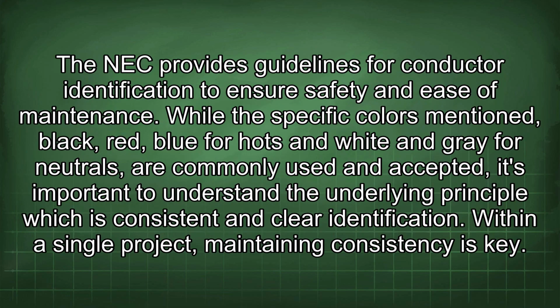The NEC provides guidelines for conductor identification to ensure safety and ease of maintenance. While the specific colors mentioned, black, red, blue for hots and white and grey for neutrals, are commonly used and accepted, it's important to understand the underlying principle, which is consistent and clear identification. Within a single project, maintaining consistency is key.